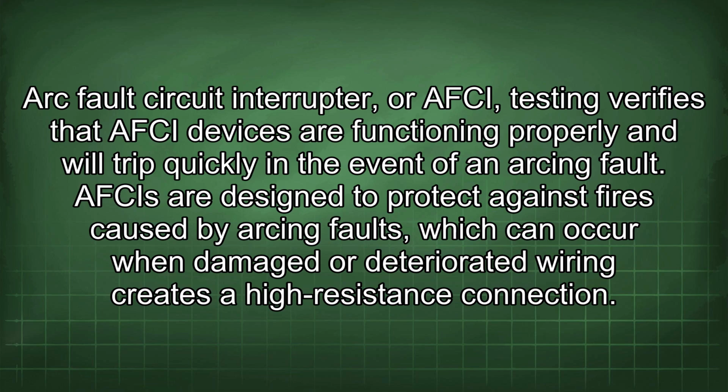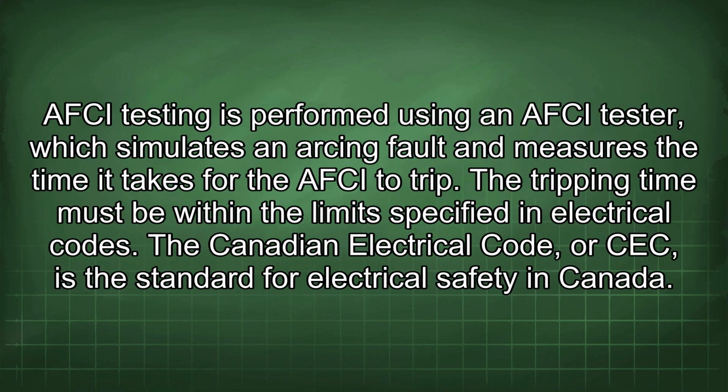AFCIs are designed to protect against fires caused by arcing faults, which can occur when damaged or deteriorated wiring creates a high resistance connection. AFCI testing is performed using an AFCI tester, which simulates an arcing fault and measures the time it takes for the AFCI to trip. The tripping time must be within the limits specified in electrical codes.